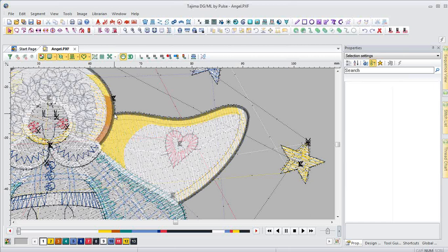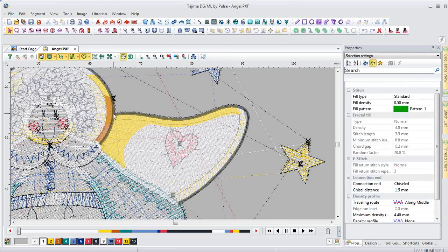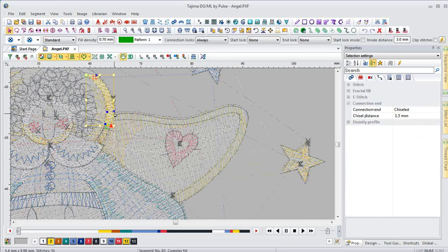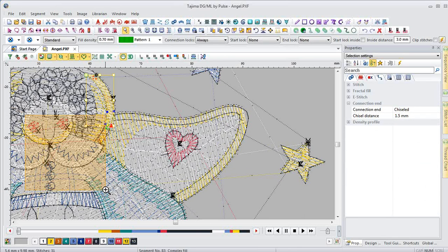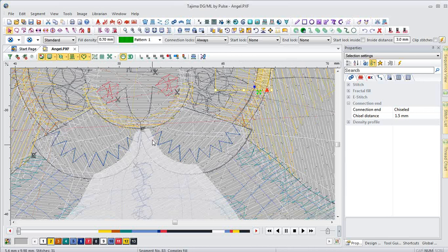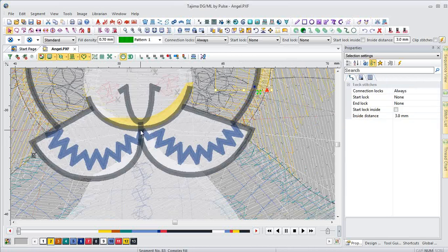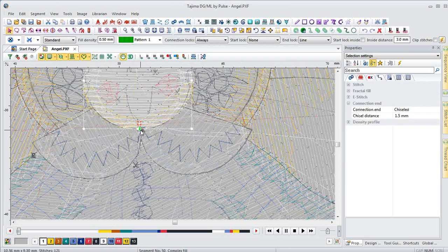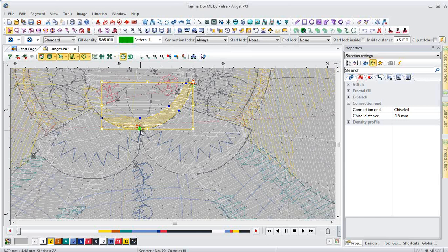A nice thing about version 14 is that I place my mouse, as you see here. I can see all segments coming in this point. Clicking with my left mouse button, the system is going to show me the segments which are coming in that position. For example, if I move here, I can see all the segments coming here, and I can start selecting by just clicking my left mouse button. So selection is easy, fast, and straightforward.